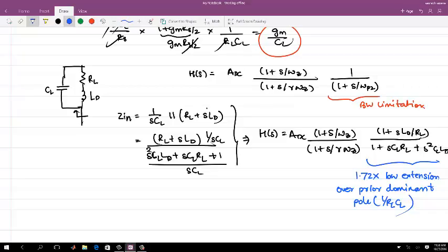Okay, don't take it on faith. Let me just give you an example. So let's say I have this channel response and this is Fs by 2. I use an equalizer such that I get a flat response till here, let's say ideally. Okay, and then I have another equalizer where I actually got this, which is not flat, but you are actually getting a wider bandwidth. So what do you think, which will perform better? How can you comment on that just by looking at the transfer function?